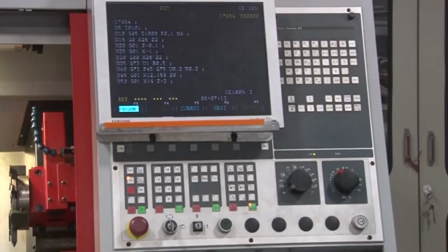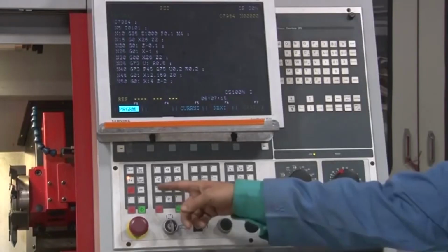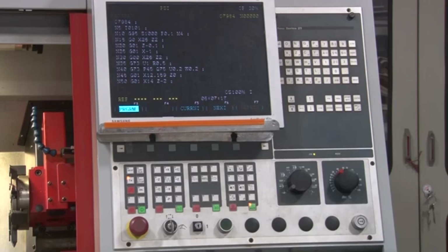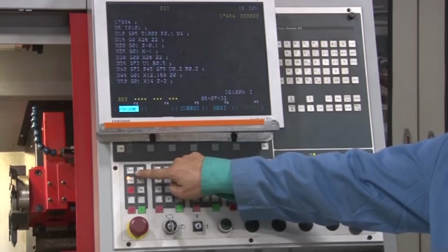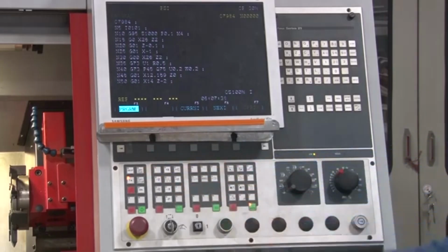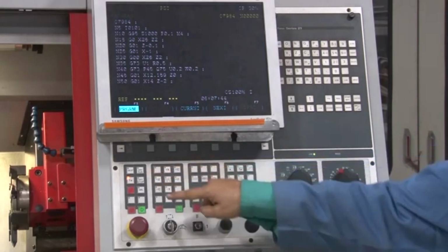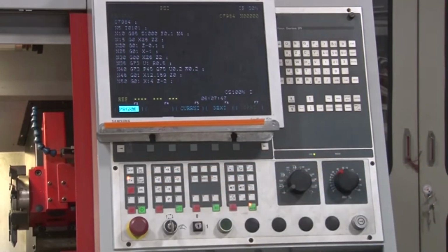Okay. So, this is the machine control keys, and if you see that in the panel there are different kinds of knobs, and those knobs are indicative of a certain function which the machine has to perform. So, for example, one is the skip. Skip blocks will not be executed. If you put the skip, that particular block which is in the program will not be executed. Now, the next is the dry run. Dry run, this is the test run of the program, if you have to do that.